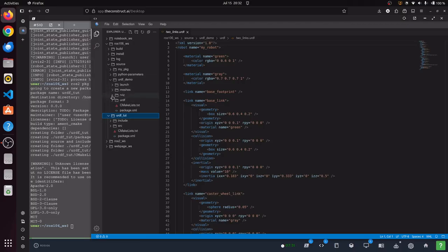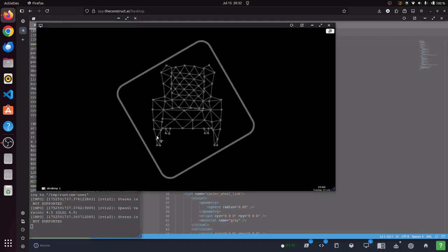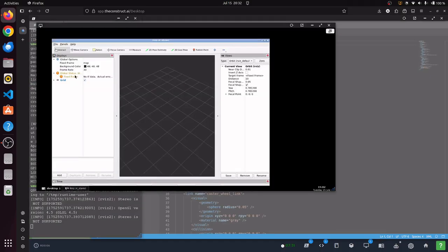Okay, so this RViz folder is here because when you run RViz, let me show you again. When I ran RViz earlier, you saw this window, right? You see this thing, no TF data, and some kind of error. It shows an exclamation mark, right? So what happens is you need to change some settings in RViz so that you can visualize your robot. Now obviously there is the error that there's no robot to visualize, so it's obviously going to give an error.